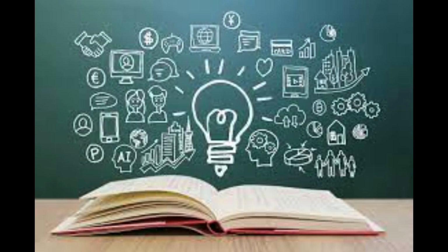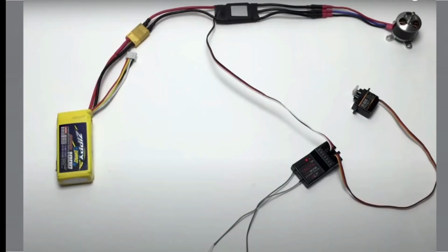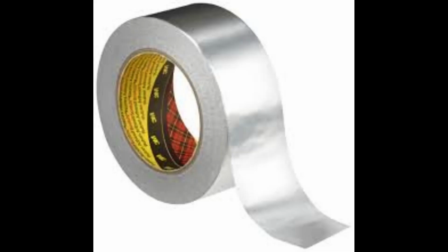We learned lots of valuable information from watching our plane crash. The first thing we learned was that it's very important that all of the internal components, like the battery or speed controller, are secured and fastened inside of the plane to stop them from moving around the fuselage. Another thing we learned is that it's very important to make sure that everything is working to the best of its ability before you test it.